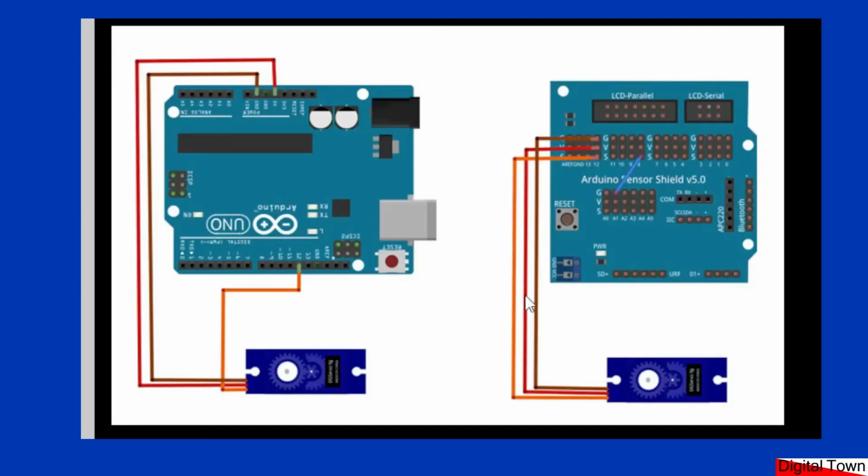So if you're not still traumatized from that terrible phone video, I just thought I'd better go through the wiring with you. As you would have seen, my servo was attached to an Arduino with some wires stuck into the plug. It was basically this setup here. So the orange wire, the signal, was going to pin 12. The red wire, 5 volts, is going to the 5 volt pin on the Arduino, and the brown wire was set to go to ground.